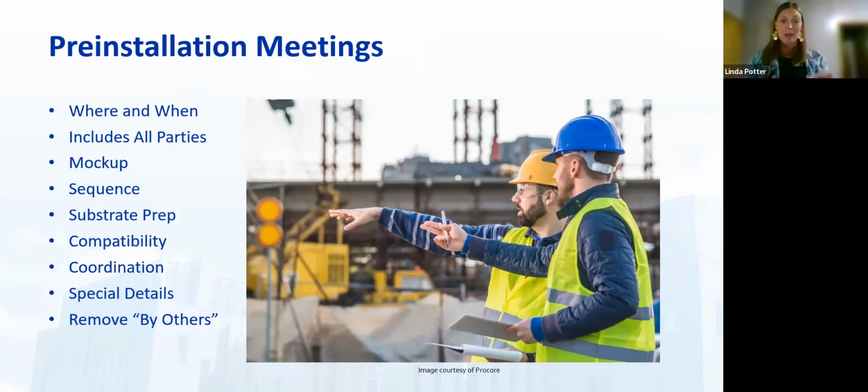The substrate prep, we're going to talk about that there. Compatibility between all of the materials. Coordination of who goes first and when do they go first? How much time is needed between to cure? All of these things, we're going to work through those special details. Because you can look at all of the manufacturer's details that are out there, and inevitably they don't match every single as-built condition, it feels like.